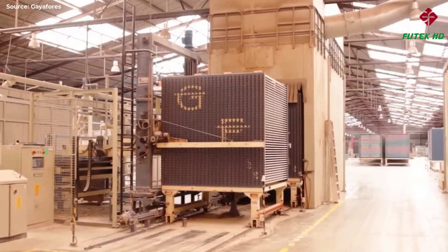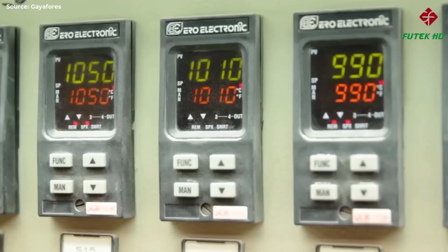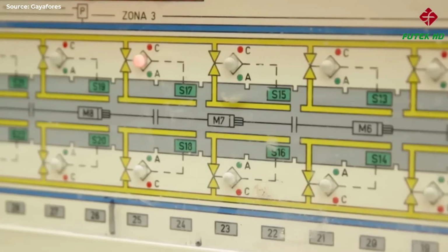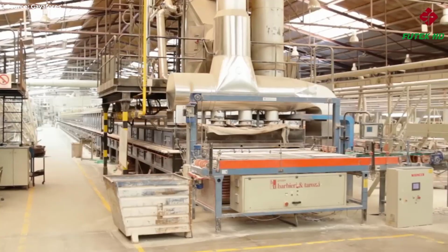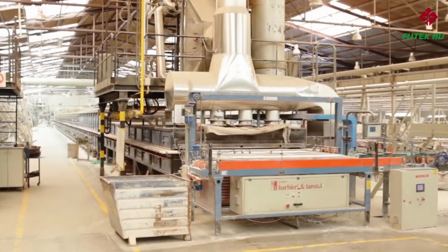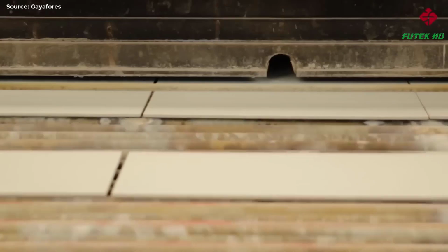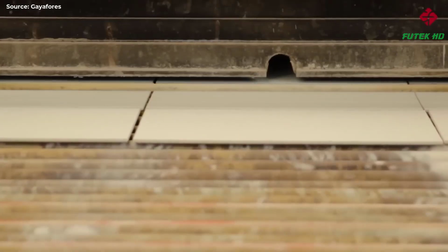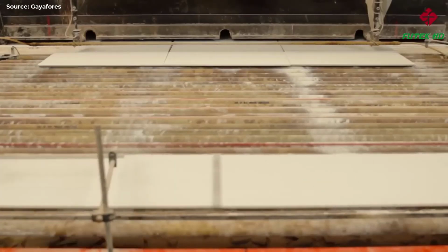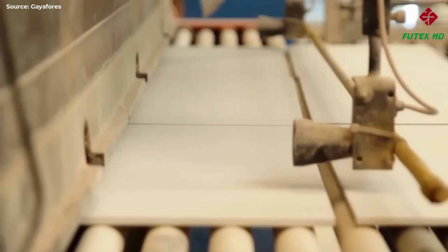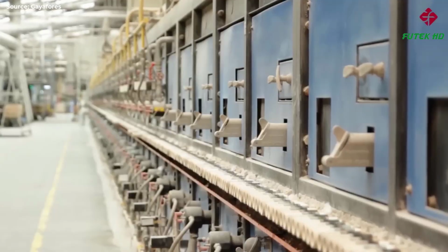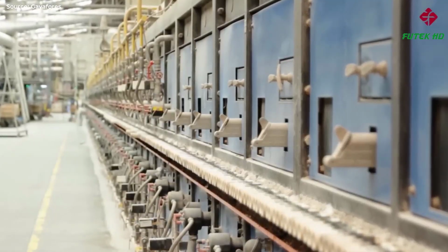Firing. Firing is a crucial step in the ceramic manufacturing process, solidifying the tiles and enhancing their durability. The tiles are fired in single-layer roller kilns using very fast firing cycles of about 45 to 60 minutes. These kilns, which are gas-fired, feature a relatively low yet wide chamber and can accommodate a large number of tiles simultaneously. The maximum temperature during firing ranges between 1,100 and 1,200 degrees Celsius.